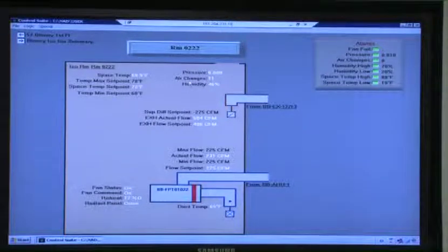And then air changes 11 calculated, humidity 46%. Excellent. The alarm settings that we have on the air changes, we've picked arbitrarily based on what values we actually have for air changes. We really need to identify what each room needs to be for air changes and alarm conditions. We can work with you on that, but the set point's adjustable, we just pick numbers at the moment.